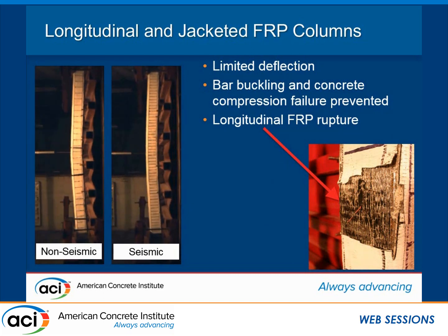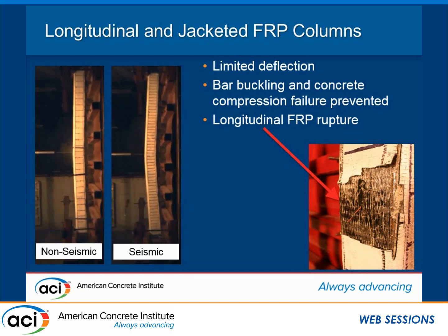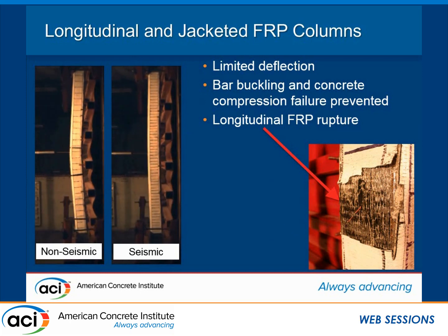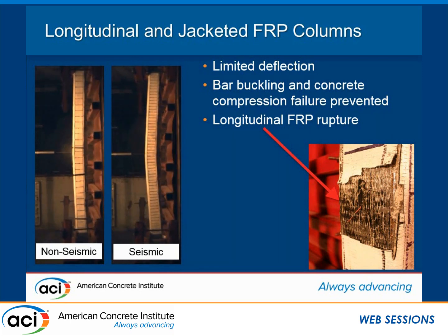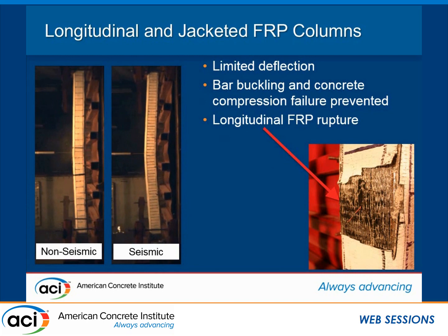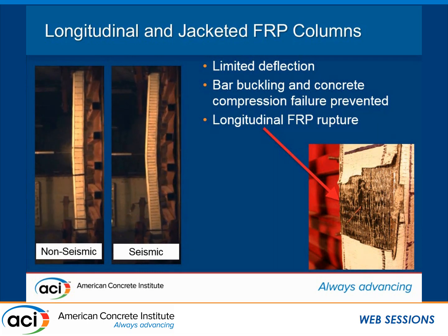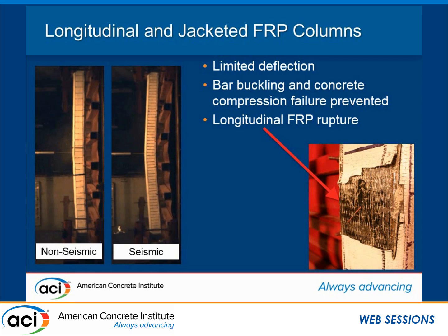And there's a lot to this, a lot of different design parameters you could take. You could add many, many layers of FRP under this, and then would you rupture it or would it debond before the confinement effects of the jacketed FRP was able to hold it in place long enough for rupture to occur? So there are obviously many different parameters that could happen here. But what it does show is that you can gain the benefit of stiffening and then also the benefits of post-failure ductility.